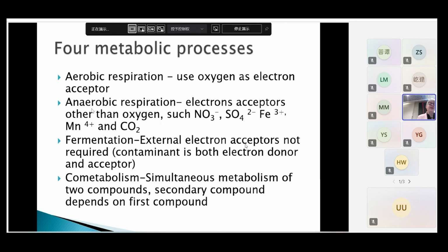Procedures, as usual: site investigation, do some treatability studies, see whether you can recover as much of the contamination as possible first, and then you can implement an in situ system if all things seem to be positive, and do the monitoring and performance evaluation over time. So aquifer characterization, biological characterization, and contaminant characterization. The bacterial characterization is the added step that we haven't mentioned before.